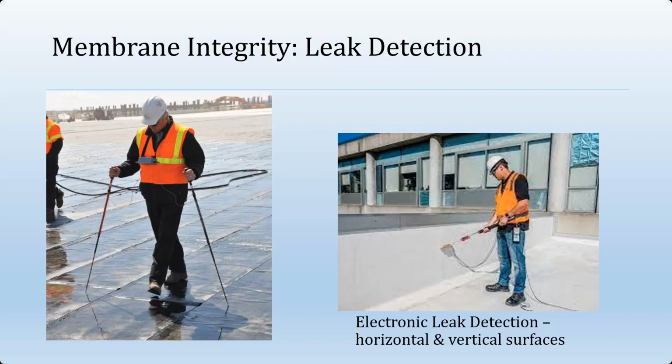And then a leak detector with these voltage indicators simply traverses the deck, much like you're cutting the lawn. And when they find a spike in the current, an audible chime will come up on that thing that's around this guy's neck, and he'll be pretty much right on top of the breach. And it's a lot easier to locate the leak at that point and effect the repair. So it's a lot faster. Time is money, as opposed to having to do the flood test.